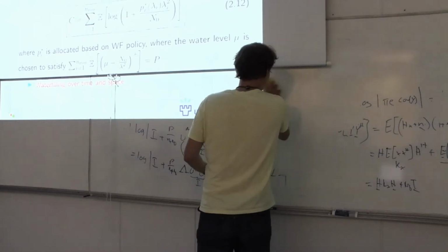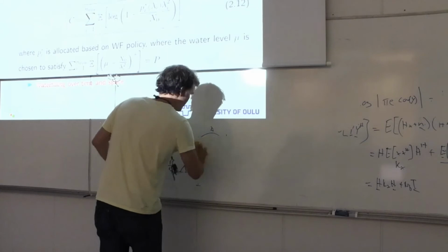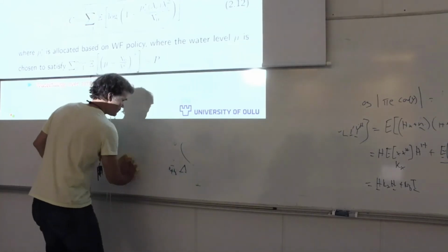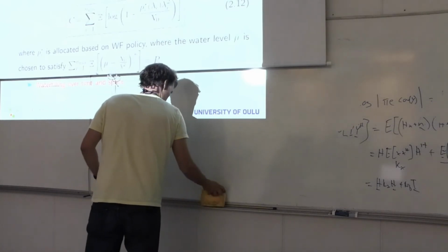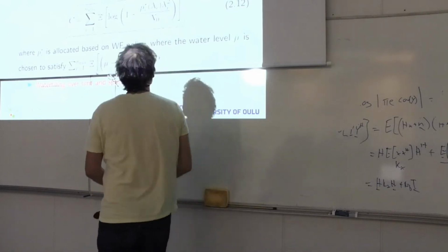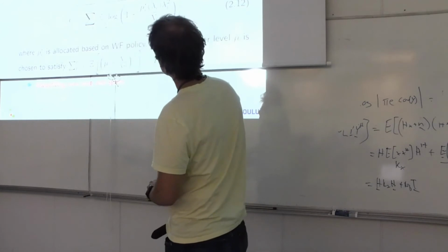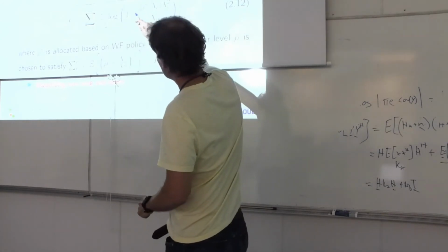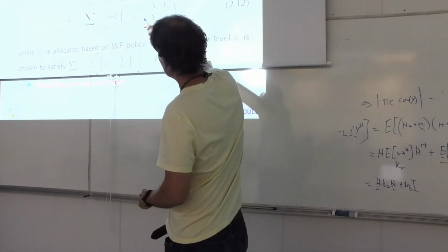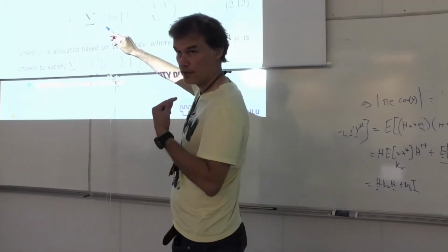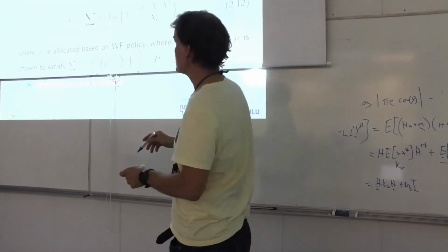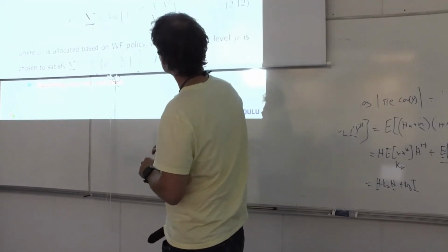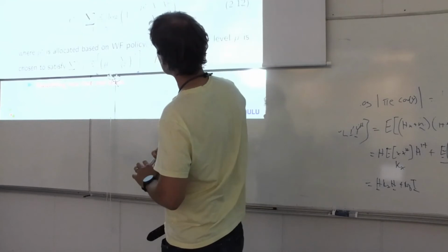CSI is just complementing that. It's the SVD solution. So now we know that when we know the CSI, Q should be chosen to be the right singular vectors of the channel matrix, V, and P is the power loading matrix.